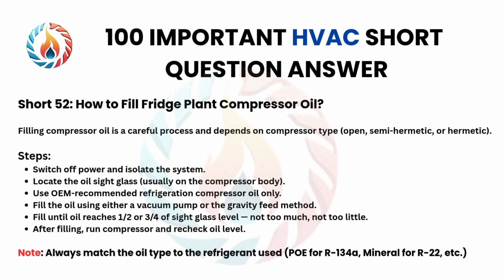Short 52. How to fill fridge plant compressor oil. Filling compressor oil is a careful process and depends on compressor type: open, semi-hermetic, or hermetic. Steps: switch off power and isolate the system. Locate the oil sight glass, usually on the compressor body. Use OEM-recommended refrigeration compressor oil only. Fill the oil using either a vacuum pump or the gravity feed method.